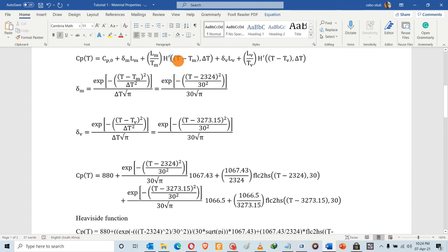Then it is a function of a change in the surface temperature and the temperature differential. And then you account for latent heat of vaporization as well. It's a similar representation, and the only difference is you are only including now the vaporization properties like temperature of vaporization and the latent heat of vaporization.